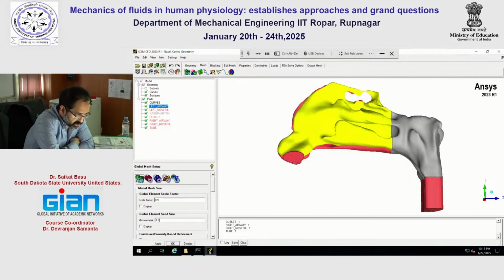That's why whatever settings you introduce here, you need to still keep track of how many total number of elements are being generated, what is the overall volume that would give you the mean size of each element, and based on the kind of venue journal that you go to, you might have to justify why you chose your mesh element size the way you have.